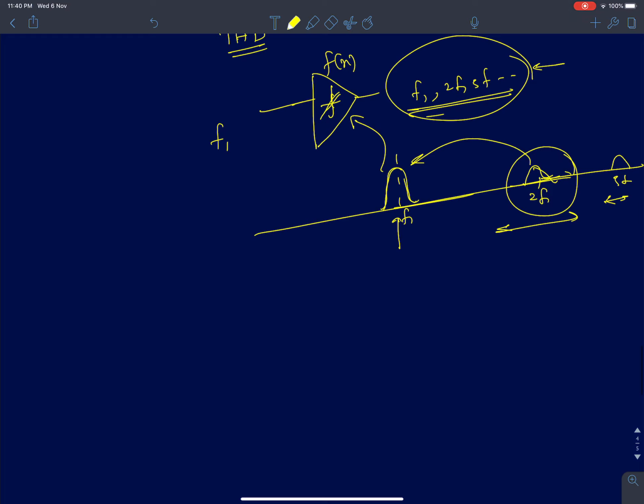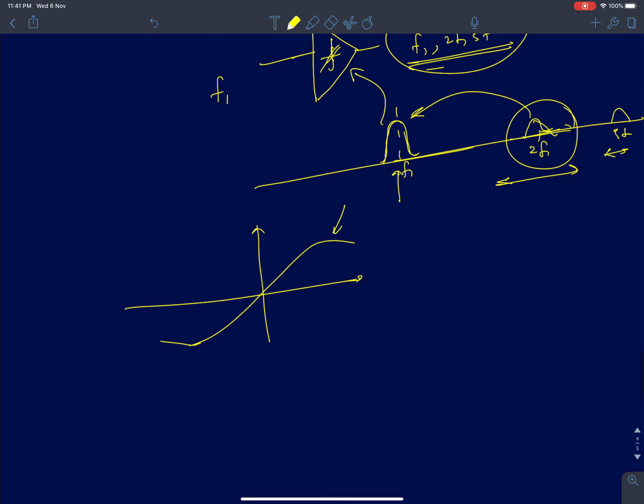Then we also discussed an important parameter called nonlinearity, where the gain saturates as you keep increasing the input signal. Okay. And we said this is a compressive nonlinearity, and we took the example of one of the most commonly encountered compressive nonlinearities, which is third order nonlinearity, odd harmonic non-ideality, characterized by this equation k1x minus k3x cube. Okay. And we said why did we choose this?